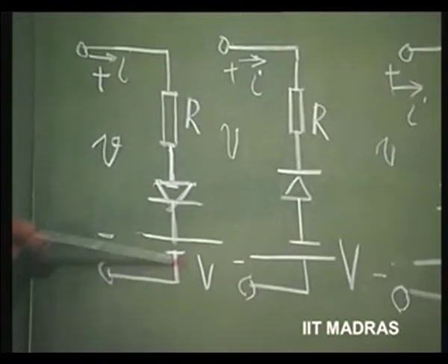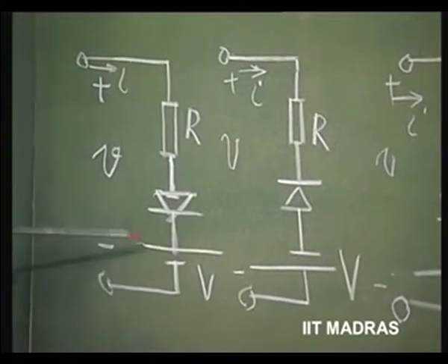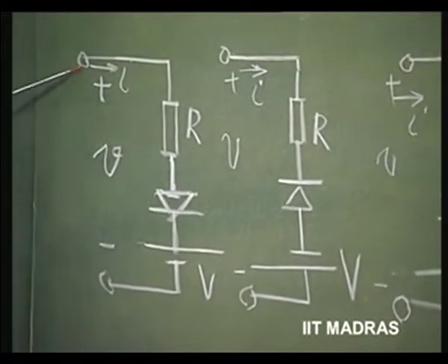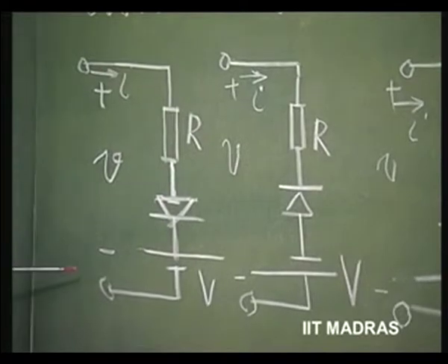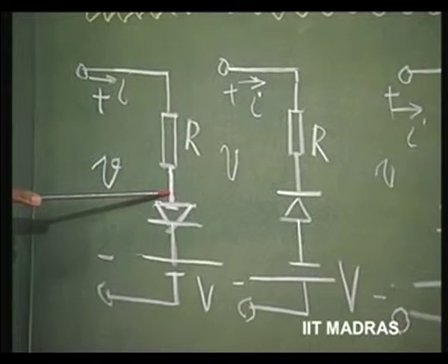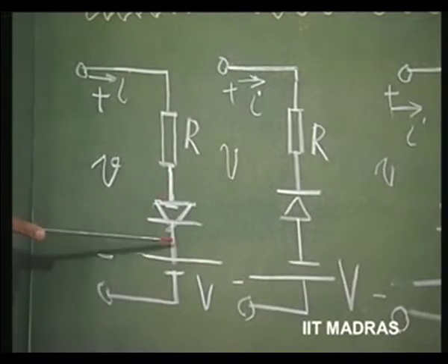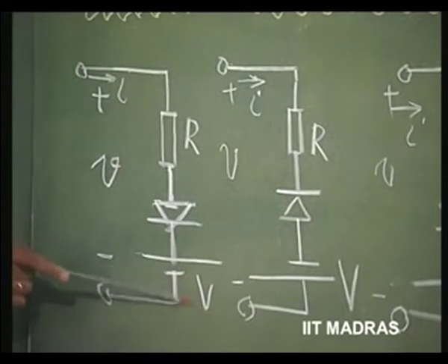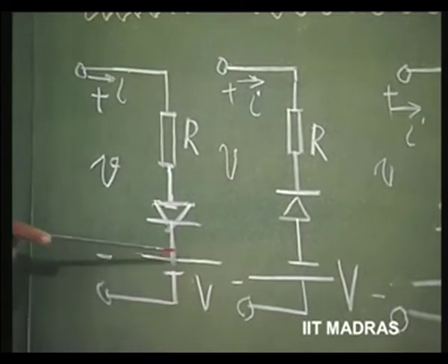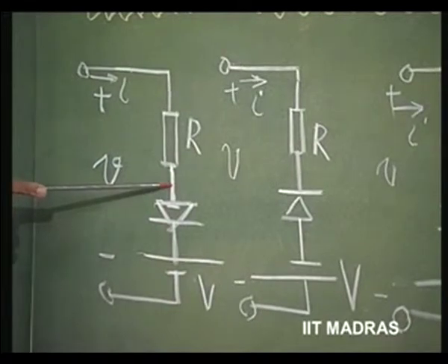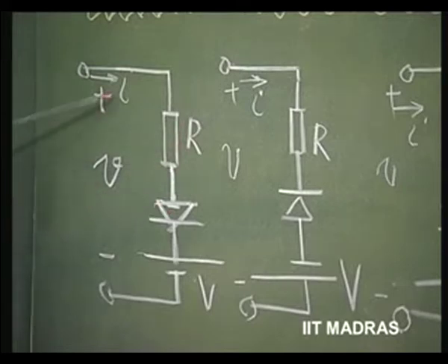This is the block that we have already used in example 4. If this voltage is positive and this current is defined this way as positive, then this diode is going to conduct when this voltage is higher than this voltage by this magnitude, whatever battery voltage we are connecting here. If this is 1 volt, when it goes above 1 volt, this diode is going to conduct, and this resistance will come into the picture above that voltage. So, this we had used in example 4.